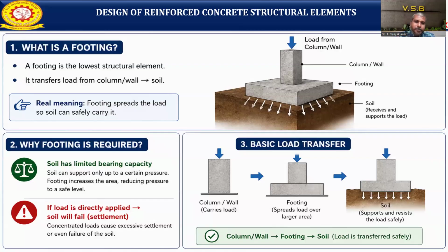Then why is the footing required? The soil has a limited bearing capacity. The bearing capacity of the soil is very low. In an area, different types of soil will be there, and each and every type of soil has its SBC, safe bearing capacity.